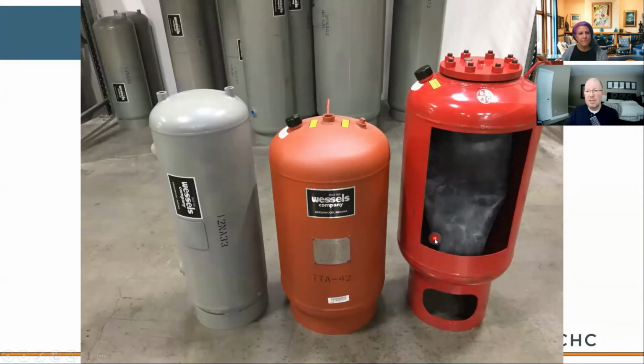That's just a classroom display. Don't let that throw you. It just shows that there's a rubber bag inside the tank. Each one of these, you've got a system connection kind of at the top, and this one is down at the bottom, not to confuse you. And under this rubber cap is where you're going to find a Schrader valve or an air charge to add air to the outside of our bag or diaphragm.